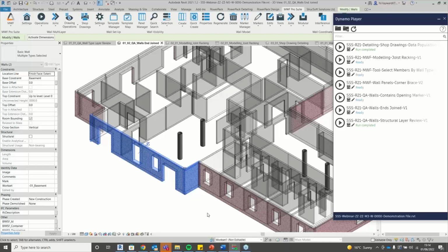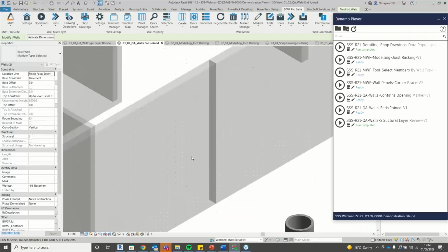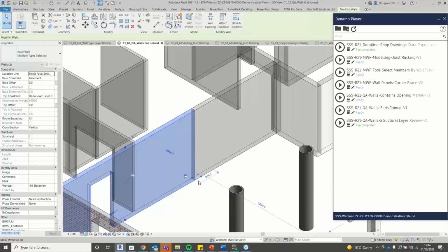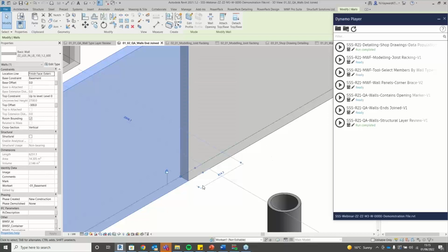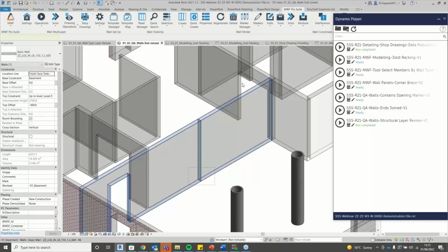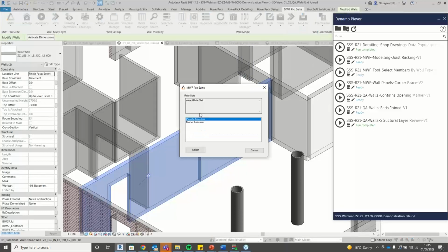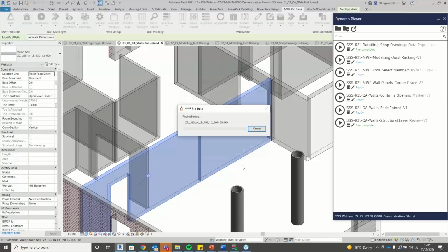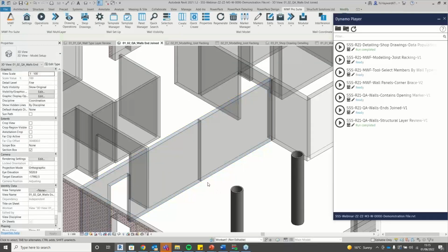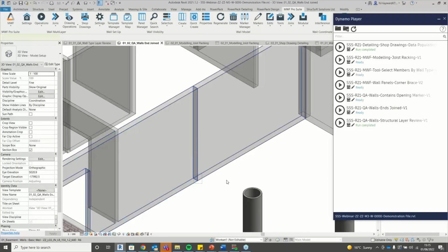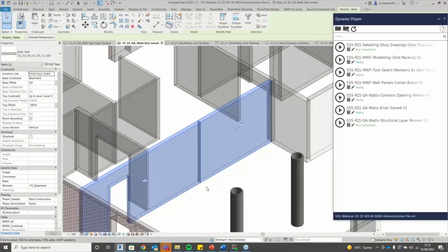So what Natalie's going to do here is give us a little example by selecting two of the walls in the internal part of this project, which we would ordinarily assume wouldn't get a join marker, just to try and tease out this error. As you can see, the wall is disallowed on one end. So when Natalie tries to use the auto join in this case, we're probably not going to get a join naturally, because the wall join status is disallowed. But there are times where that disallowed wall end can create some sort of confusion within the project.